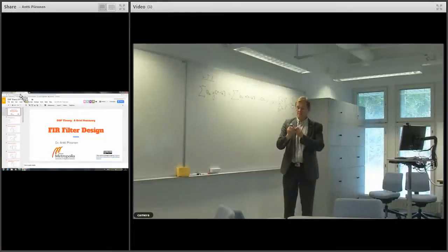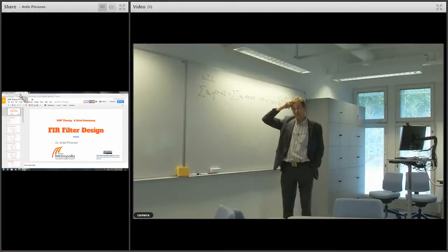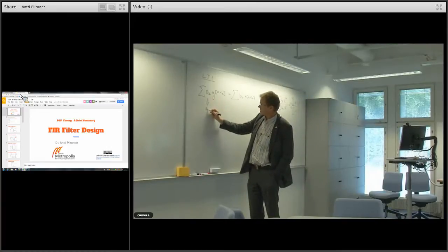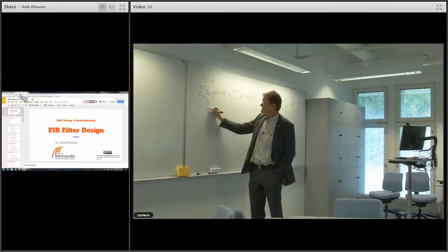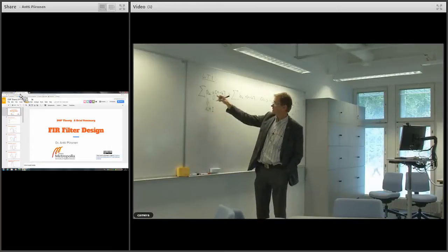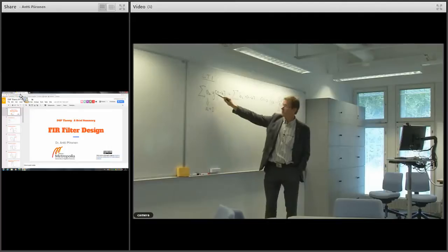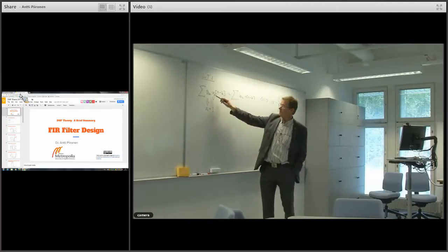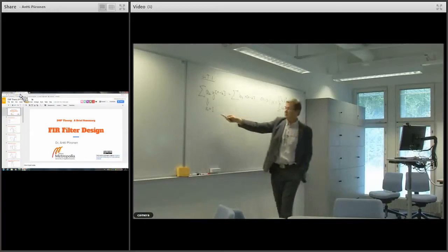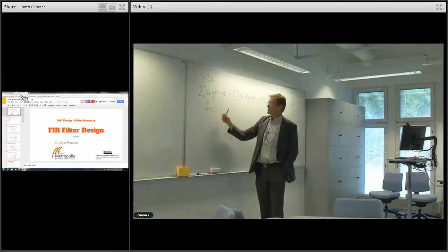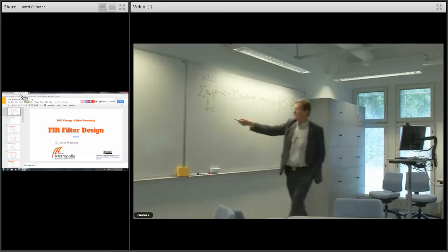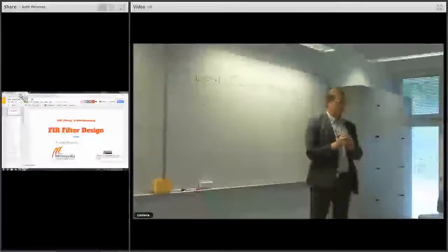One thing I noticed as a small problem on the exercises was that sometimes, for some reason, a0 goes to 0. It's never 0. a0 is usually 1, which comes from the fact that usually the difference equation is derived from an equation where you have y[n] on one side and everything else on the other side. If you have a0 as 0, then you wouldn't have the left-hand side at all. You cannot then calculate any y[n] there. So that's one noticeable thing here.